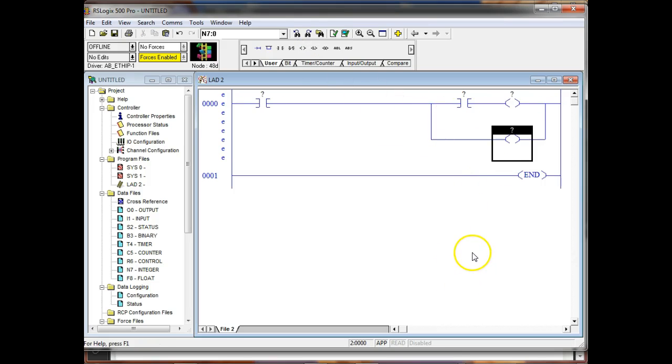So is that it? Yep. That's it. Here we're going to assign it an input. So remember, if you're on the 504s, your input module is 1, right? You understand? Your output module is what? 2. If you're on one of the 1100s down there, or if you're on one of the 1000s, then those are 0. Your inputs are 0 and your outputs are 0.